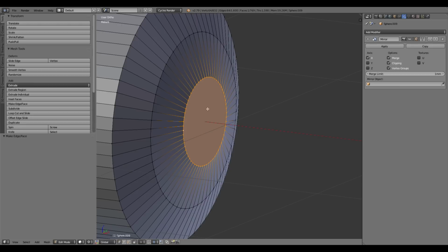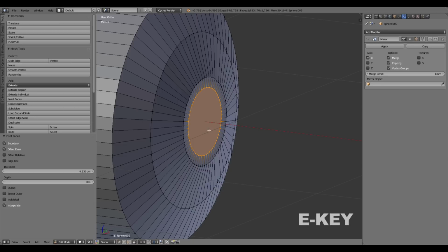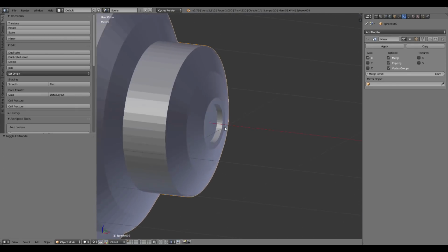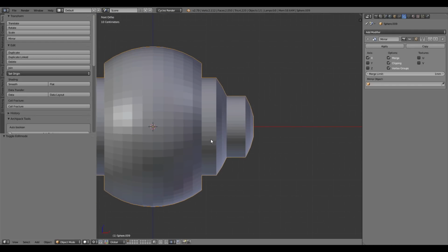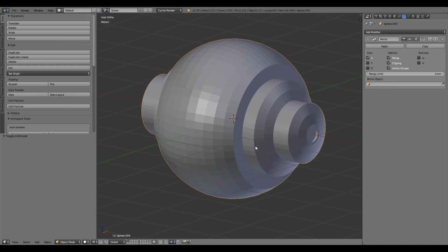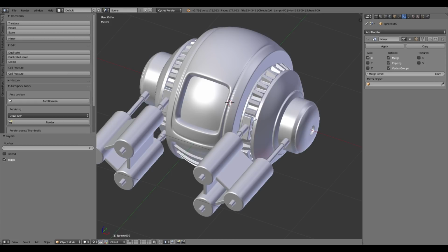And it's really easy to handle because if we did something like an inset or an extrude, all we've got to do is hit I, and then we can scale that in, okay? And hit E, and that extrudes that face. And so we can actually inset any number of faces all at the same time by having that n-gon. That's pretty handy in a modeling scenario. So far, we're actually getting this model created pretty quickly. So obviously, the next thing that we want to model, this groove and this cog, okay?